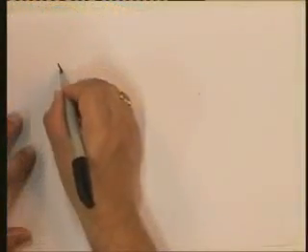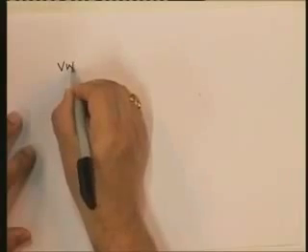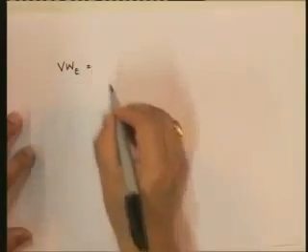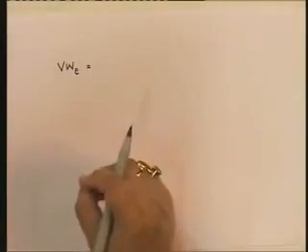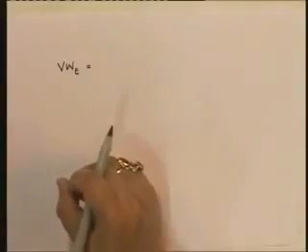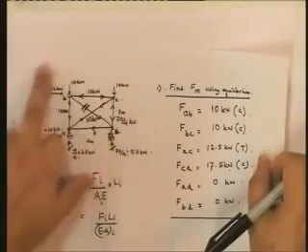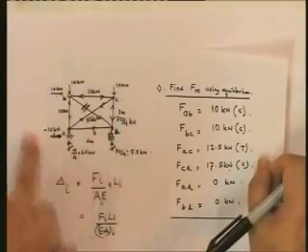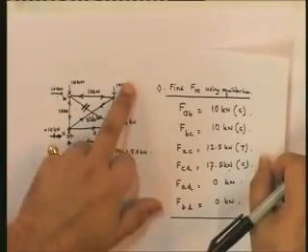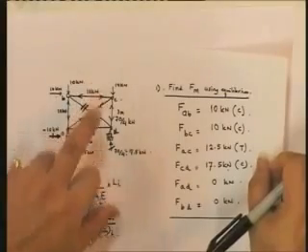The virtual work. What is the external virtual work? External work done by all the external forces. Understand, this is the real structure, because I'm trying to find out the displacement at this point because of all these forces. So this is the real structure. So I need to find out the real displacements and real deformations.